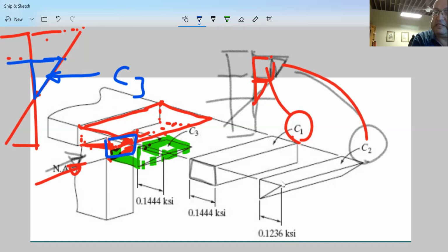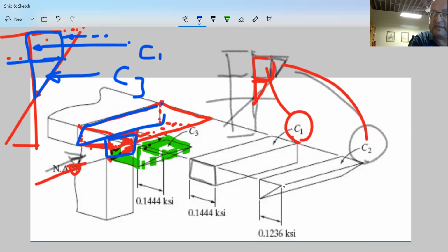In the top, this is now trapezoidal applied on the flange. So it's gonna be kind of a little bit of trouble. So I'm gonna divide it into 2 sections. One of them is gonna be a rectangular section, which I'm gonna be calling here C1. And then I have C2, it's gonna be right at the CG of this little triangle.